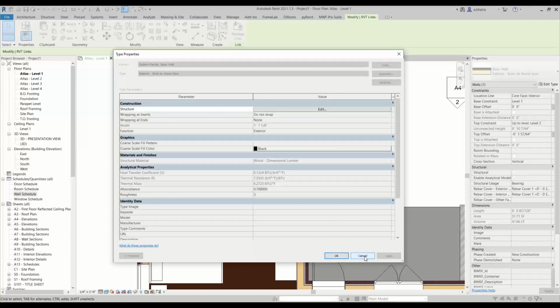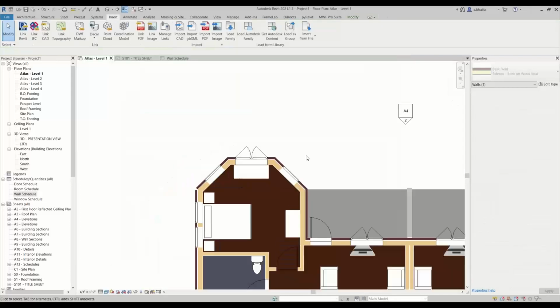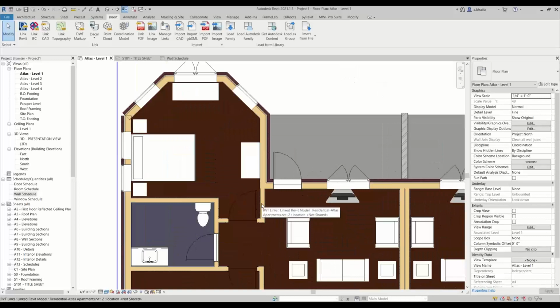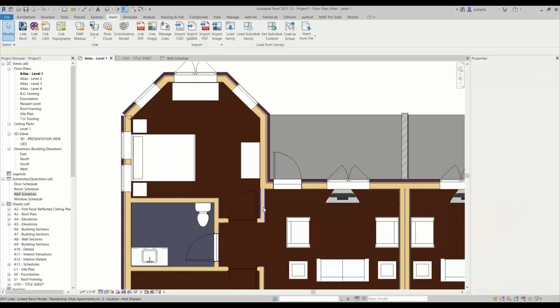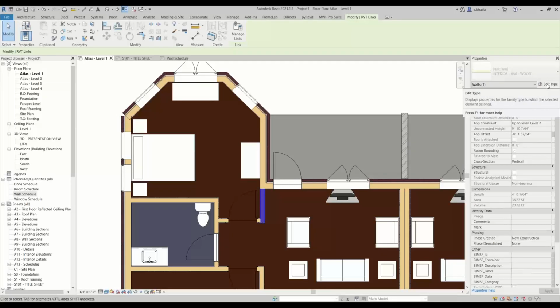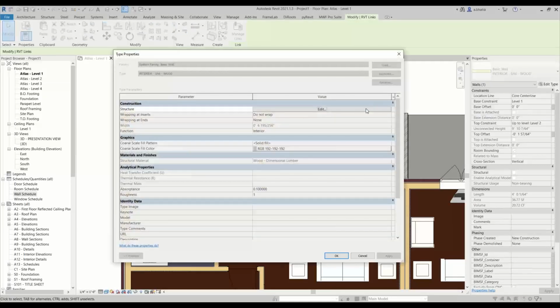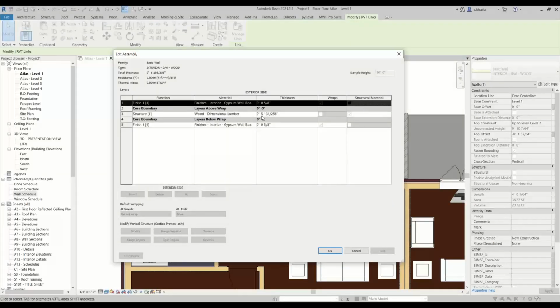7.5. Sometimes it's really random numbers like 711 over 136 or 124 or something like that. So sometimes it's super random numbers. So I like to double check and see if I can make it easier for myself. So that we have a 7.5 inch thick structural layer. So that's an 8-inch stud. And then we need a wall that is, something like this, 131 over 256. Like I need a 5.5-inch wall. I don't really care about 131 over 256. That means nothing to me, right?